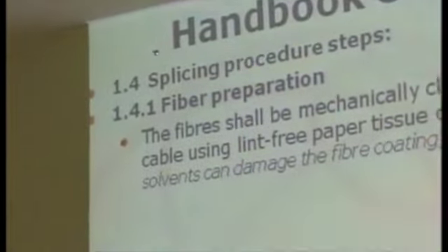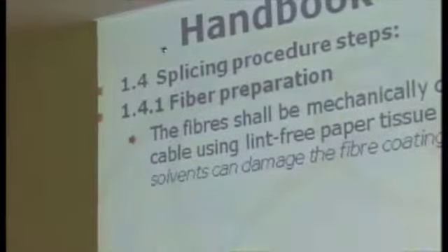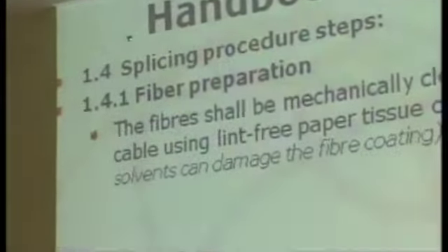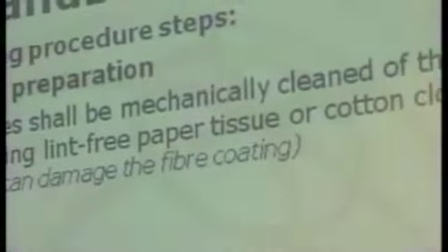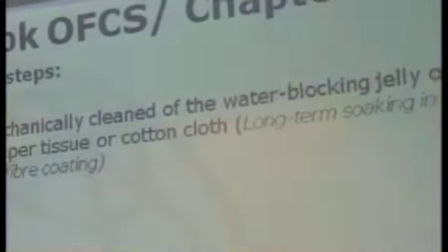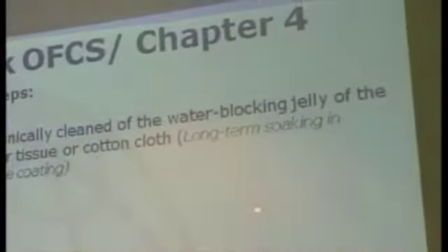Let's take care about the fiber preparation. There are some steps that need to be carefully followed to have a good splice. The first step is to prepare the fiber, removing all the water blocking jelly in the cable, using paper that does not put extra contamination in the fiber.